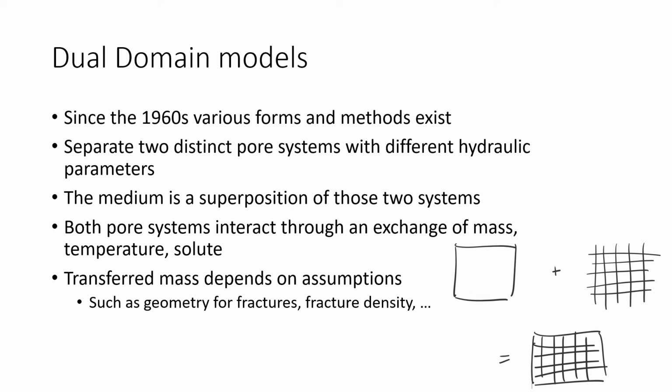Well, you can estimate what my flow velocity in my fractures is, what my pressure in my fractures is, and what my pressure in the porous matrix is, and they won't necessarily be equal, right? Which can be helpful information. Usually, for example, the storativity in the porous matrix is higher than in the fractures. So you can also see under which conditions the porous matrix is transferring water into the fracture network where it's transported more quickly, and under which scenarios, for example, the fractures will have the water flow and then store the water in the porous matrix slowly and over time.